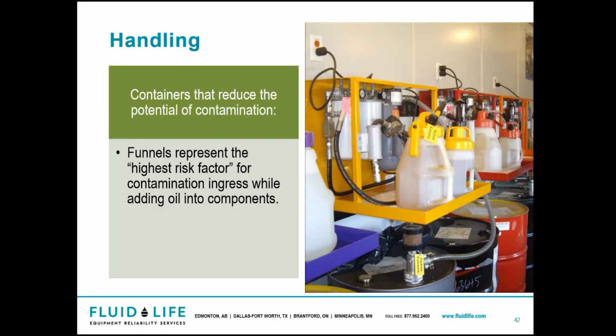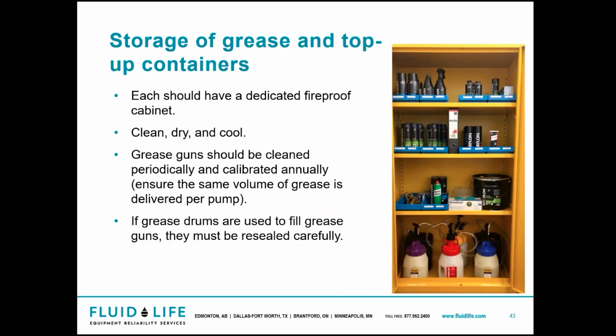And as I say, making sure everything is properly color-coded, with contamination controls in place. See how easy something like this is to set up. And it's basically filtering at every stage. You get your oil, you filter as soon as you get it, you filter it at every stage along the way. You're going to have the best program by constantly doing that type of exercise.